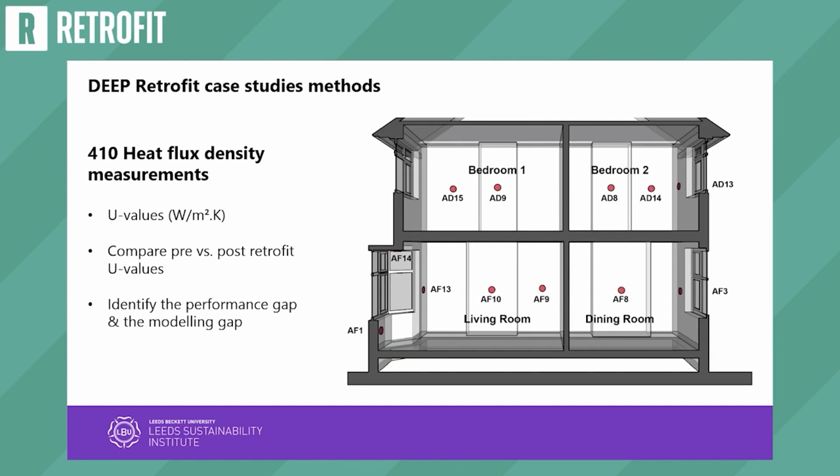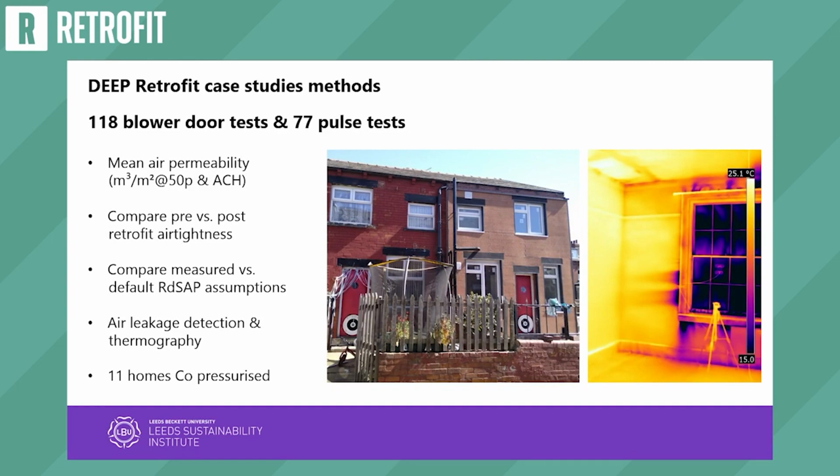So there's 3 types of heat loss. That's the fabric plane element heat loss. The second one is the one you might be aware of, and that's the drafts, the leakage in the house. So we're able to undertake some tests with blower doors, as well as some of the new test methods that are being developed to work out how much ventilation heat losses we have. And this is where we lose air through cracks and gaps in the building.